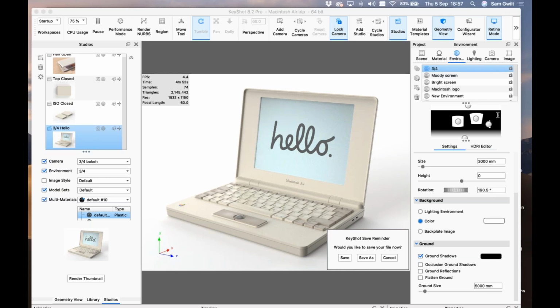But if you have an overcast day as your backplate image and the shadows are really soft in the image, it's really difficult actually to light that because it's the small things that we don't pick up on that we can never get right. So I would suggest using a photo that has got some really sharp shadows in there as well.